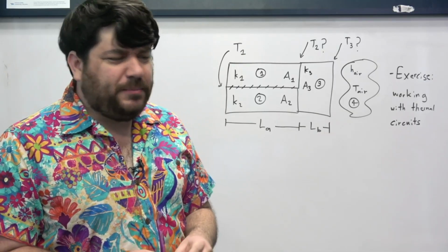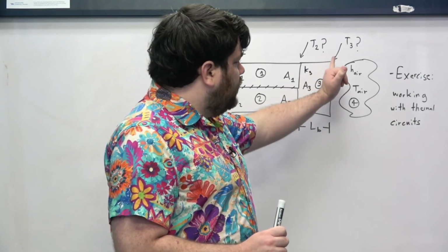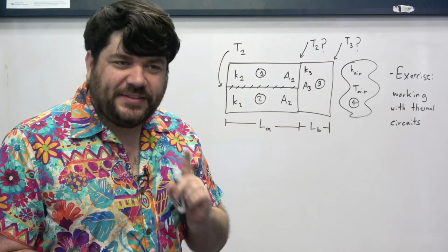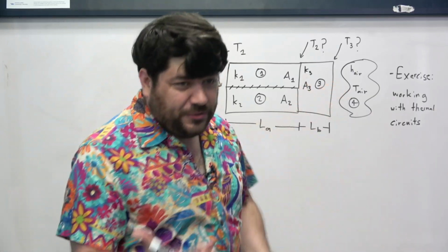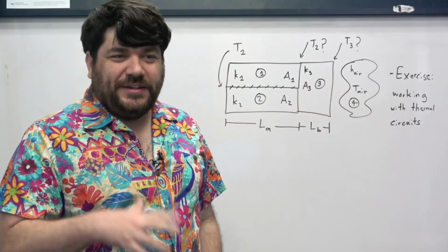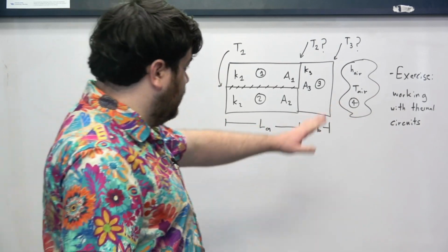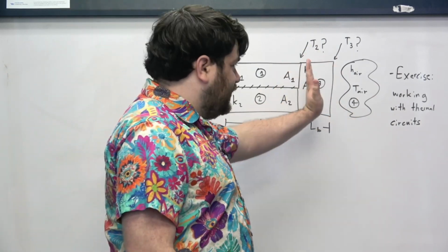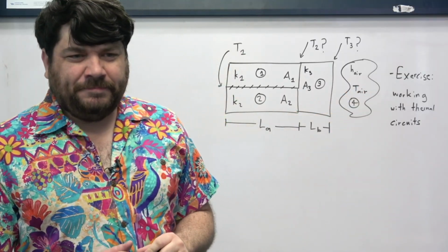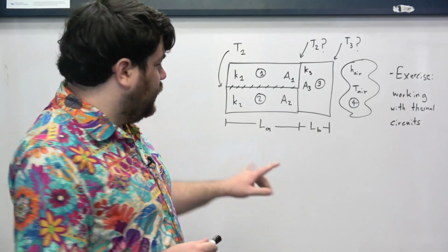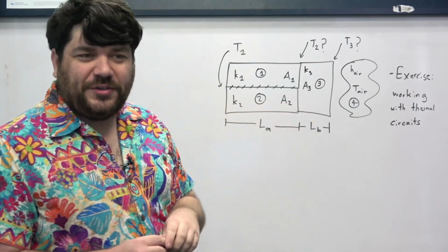And remember, like we said before, the temperature of the side of this wall that's exposed to air is not the same as the characteristic temperature of the air. If those two things were the same, then no heat transfer would take place between the edge of the slab and the air. We also have these characteristic thicknesses for each of these two little sections.